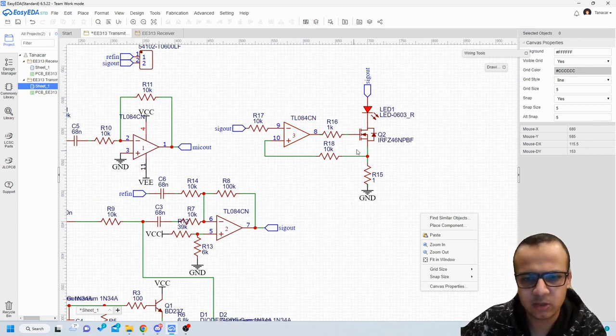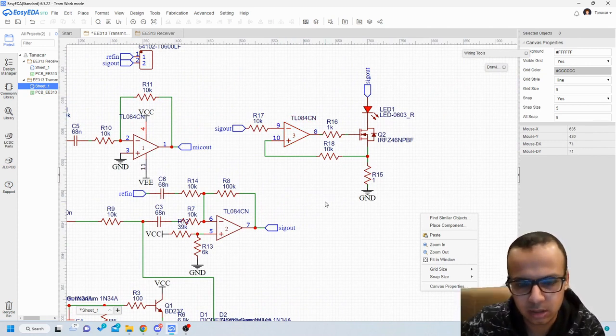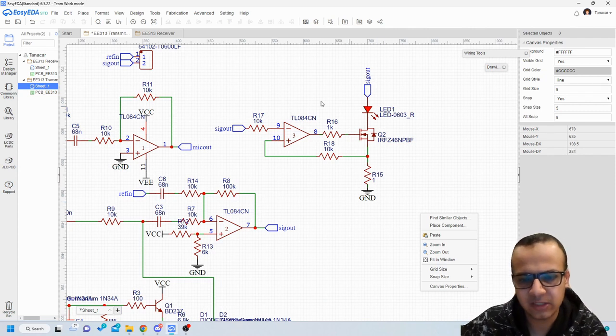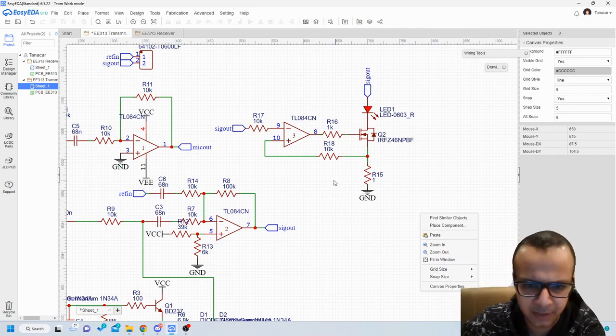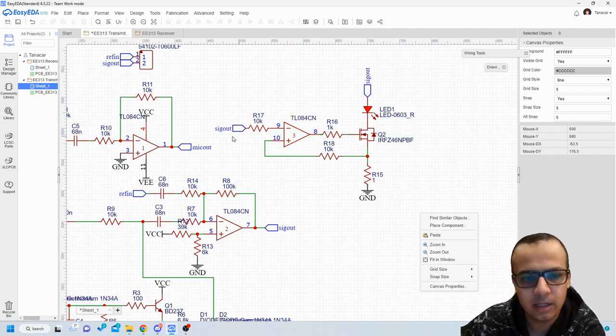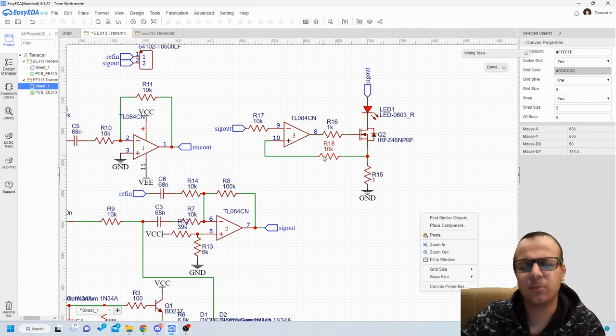After that, this summation signal will be sent to the third circuit of this unit, and the aim of the circuit is to convert our voltage information to current by using a transconductance amplifier. In this circuit, we use the linearity of the op-amp, and the signal will be fed to the non-inverting node of the op-amp, and due to the linearity, the plus side will be the same as the negative side, so this voltage will appear here. This resistor is just for protection purposes.